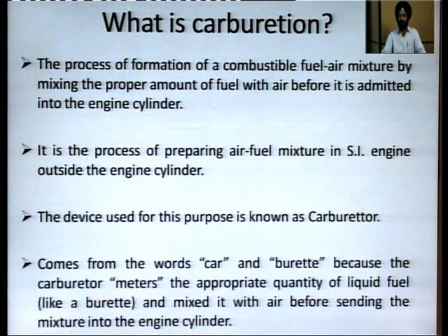It is the process of preparing air fuel mixture in an SI engine outside the engine cylinder. The device used for this purpose is known as the carburetor. The word carburetor comes from car and burette, because the carburetor meters the appropriate quantity of liquid fuel like a burette in the chemistry labs and mixes it with the air before sending the mixture into the engine cylinder. So carburetor means metered fuel air into the engine.